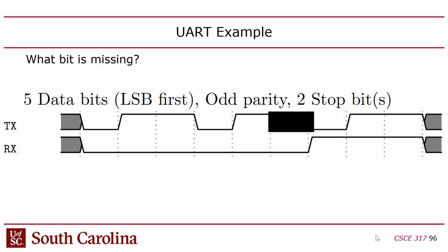Okay, so I'm just going to start at the right and work my way left so I don't get confused by these stop bits. There's a 0. So there's just counting 1 bits now. We've got 1, 2, 3. 3 1 bits. That's between the stop and the start, right? It's missing a 1. Let's see. 1, 2, 3. Well, no, that's odd parity, so it should be a 0 actually, right? Because the number of bits is already odd, so I don't have to add another 1 bit there.